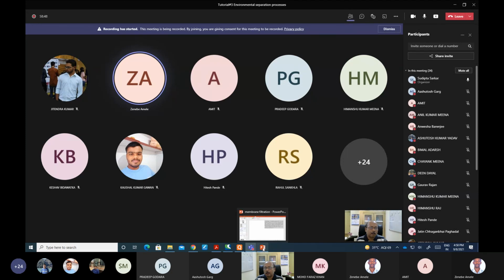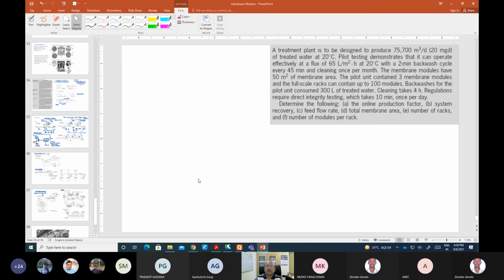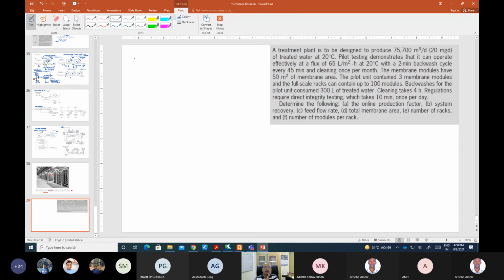It's not applicable for any kind of wastewater, sir. When you talk about clean water, obviously we use microfiltration for removing small particles, from 0.1 to 10 micron particles. So the bacteria and very small particles will be removed by microfiltration.